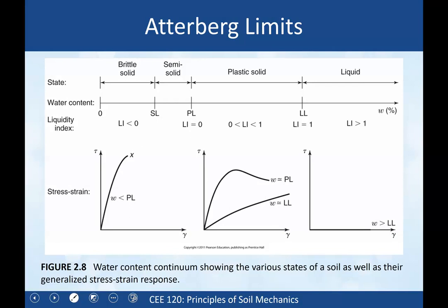All right, and here's an indication of the soil behavior. This is a chart that I already showed in my notes, and it's repeated here, along with an indication of the material response in terms of stress-strain behavior. So if you're in this zone of the plastic solid, the stress-strain behavior will be pretty weak and soft if the water content's equal to the liquid limit. Again, it's not zero, so the soil is not really a liquid. It still has solid properties, but it's very weak and soft.